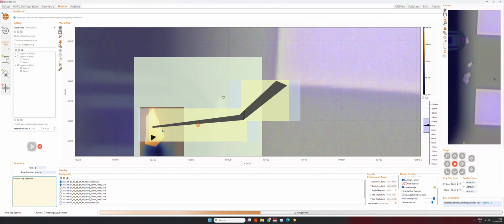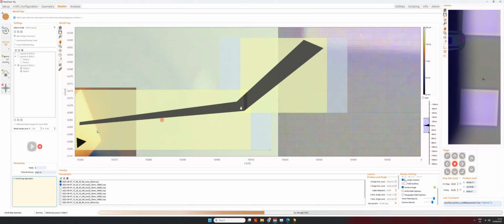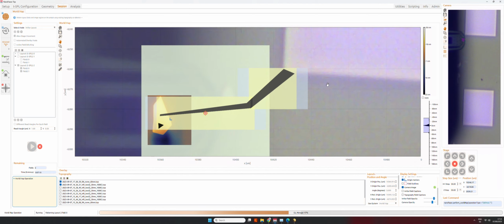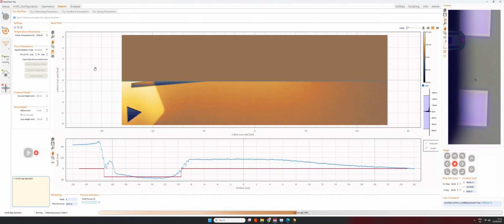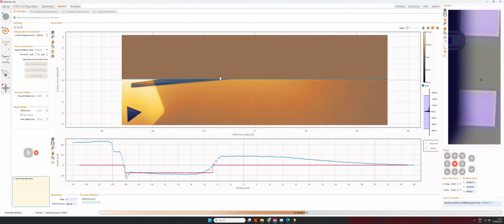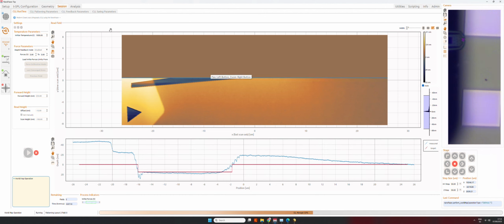While with the standard stitching process, we will write field 1, then we will move with the coarse stage, and then we will write field 2 without any reading and any alignment. This procedure is faster, but also is less precise because it has the errors that are introduced with the motion of the coarse stage.